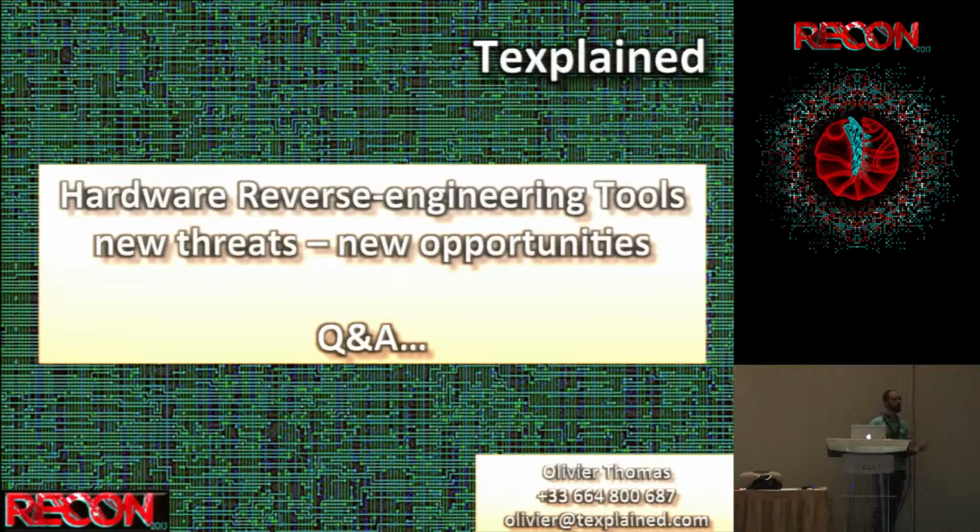So no. But for the FIB, I will rent some FIB time. I will not buy the FIB. You can even do the navigation layer. You go to somebody and say, I want to contact these points, I mark them already, and it does that for you. It's one day of work, so it's not so expensive.